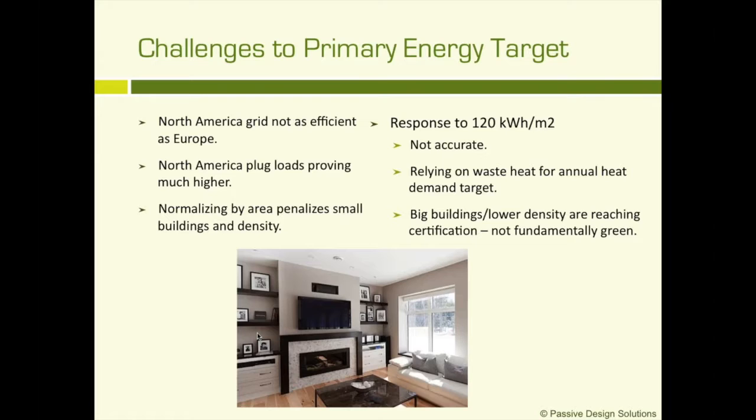One was about an 8,000 square foot office building, and one was about a 1,200 square foot house. The 1,200 square foot house had a final ACH of 0.66, and it was one of our early projects, and we thought by putting in drywall we'd squeeze out that last little bit with an air tightness strategy and drywall, but we did not reach that target. The builder was celebrating really strongly with his 0.37 air changes per hour in the commercial building. But when you compare those two on the air tightness per square foot of building envelope, the small house was actually more airtight than the big building. So again, penalizing those small buildings.